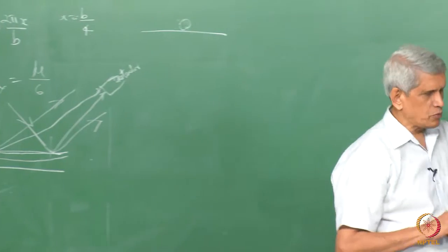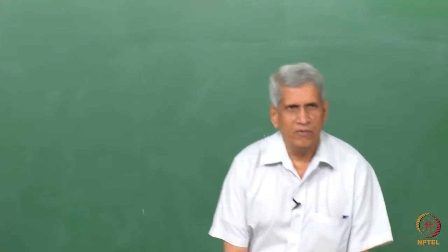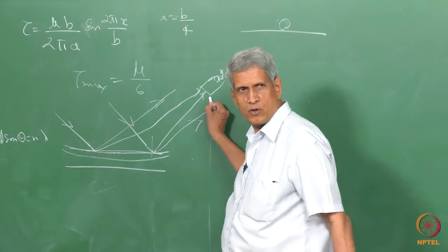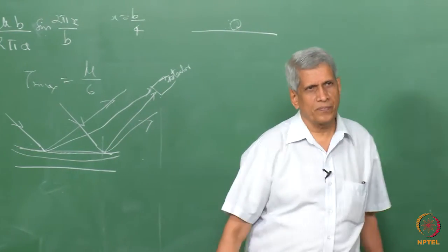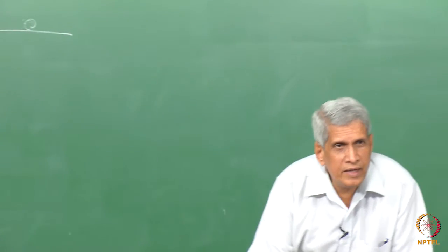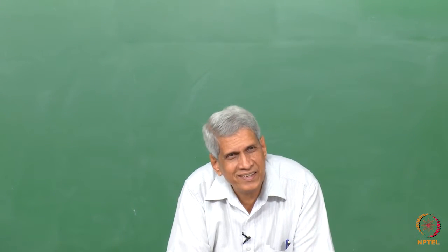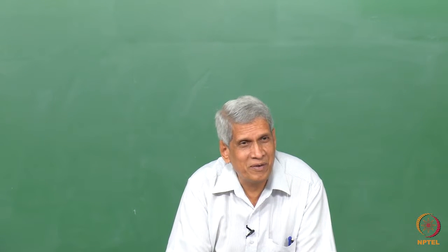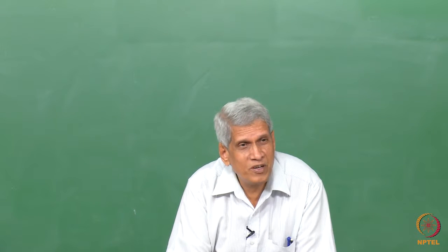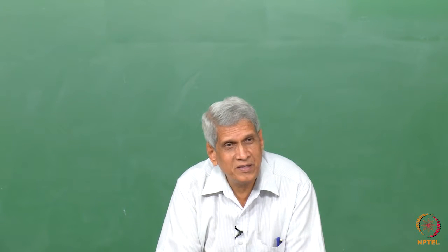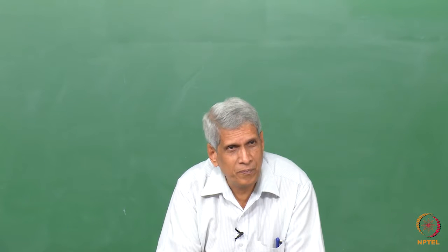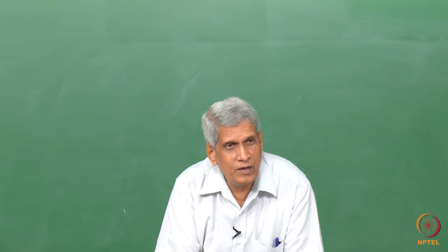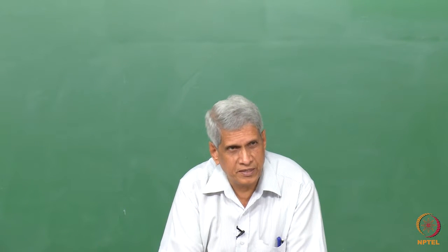A ray from here also will satisfy a Bragg angle, and will be reaching. That means that from a smaller region itself, it is not exactly parallel rays, other rays are also coming into it, adding to intensity. That means that there may be some bending within the crystals. Then what causes the bending if the crystal is grown in a perfect way? That means that some defects have to be present which are causing this sort of bending. Okay. So that is how the concept of the dislocation was put forward in 1936.